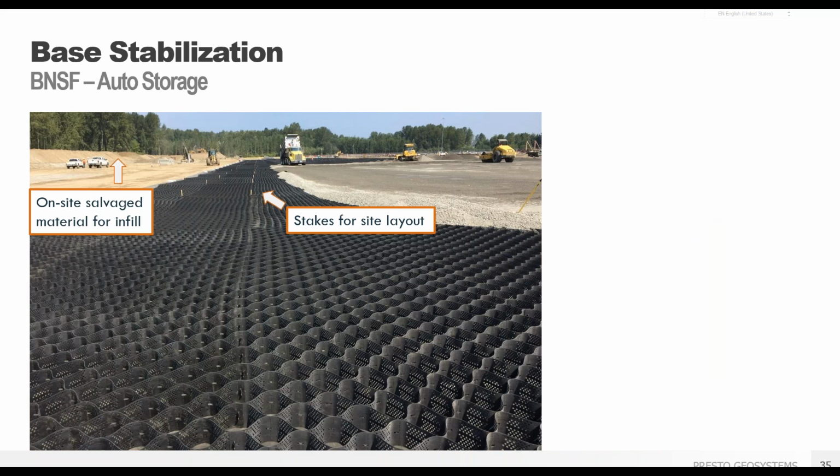Here we see a picture of the installation ongoing with a 4-inch wear surface to allow construction access during the installation process. Again, using the GeoWeb system as its own access road. At the far left, you see where the contractor stockpiled the on-site sandy soils to mix with crushed aggregate and save on construction costs. The expanded and connected GeoWeb is mid-screen, and the filling then compacting as we move to the right.